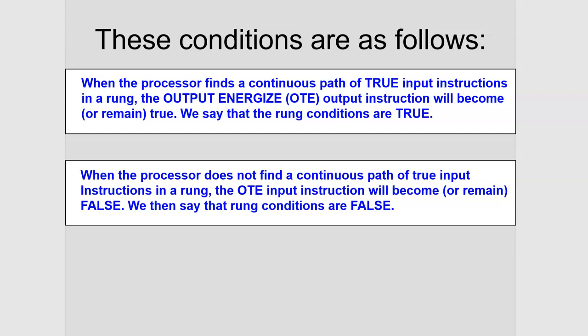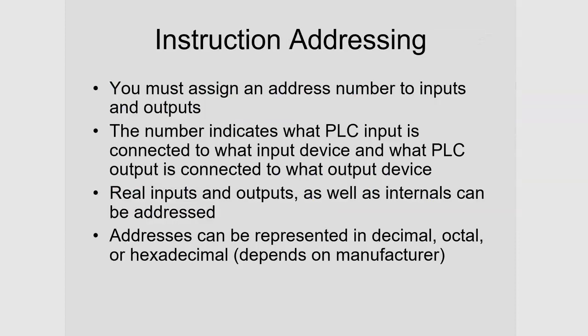This actually turns out to be pretty important. We'll talk about something called logic continuity. Logic continuity is what this slide is kind of beating around the bush and referring to. Logic continuity is a very, very important concept. A little hard to understand, but once you get it, then it makes all the rest of your programming easier if you understand that we're looking for not current continuity, not how the current flows in the circuit, but what the logic dictates. Logic continuity. We'll have more to say about that later.